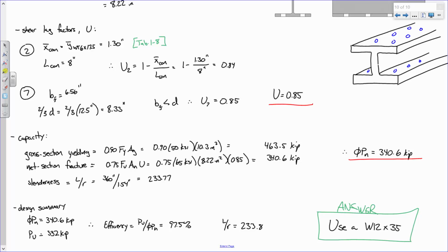That's a great question. It just depends on the complexity. Ultimately, whatever's going to win is what gives safety, construction simplicity, and the least dollar value and least construction time. So for a bridge like this, probably just use the same beam across the board. For something like that Nitro St. Albans Bridge, because it's so complicated, each member is going to be designed uniquely to tailor that load.